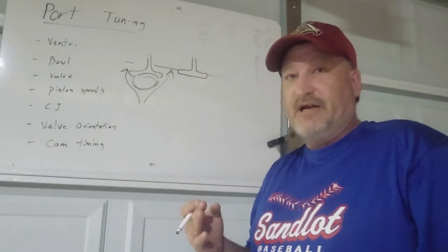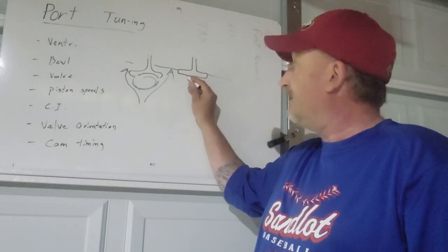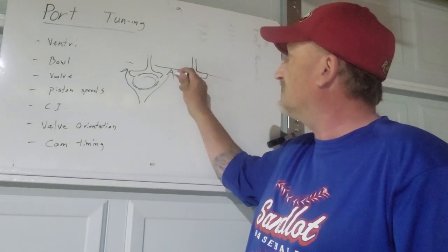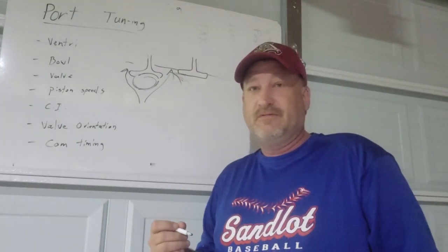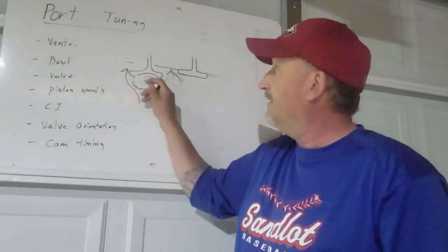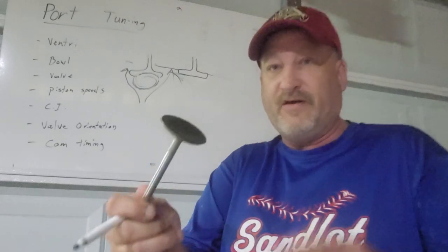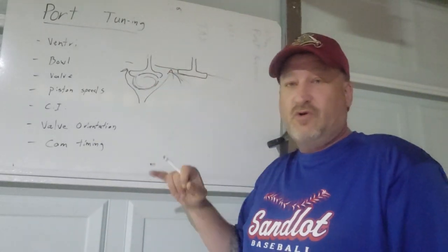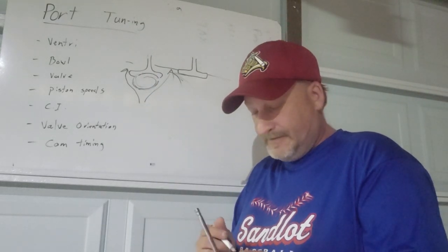As the piston is traveling up on the exhaust stroke, the valve surface area, if it is flat, is actually pushing more of the exhaust gases towards the curtain area of the exhaust. The gases that are going straight towards the face of the valve are being diverted by that force field, that higher pressure area created by the cup of the exhaust valve, to push more of the air towards the exterior or perimeter of the exhaust valve.